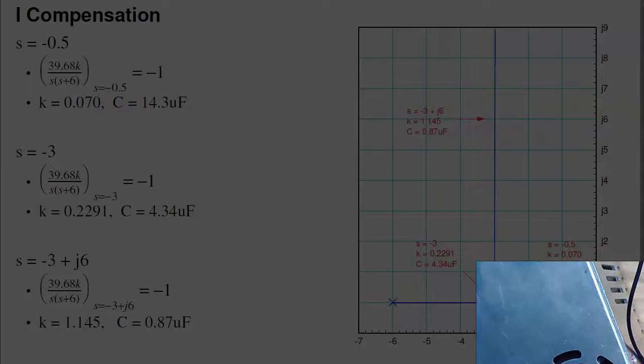So doing that, I've now added a capacitor. This is 14 microfarads. If I give it a step input, notice the motor is now slowly changing speed. It's slowing down, stopping, now reversing direction. Apply the other step to go plus 50. It stops and goes the other way. What root locus predicts is that I'll have no error for step input. This is now a type 1 system. The dominant pole is at 0.5, meaning 8-second settling time.